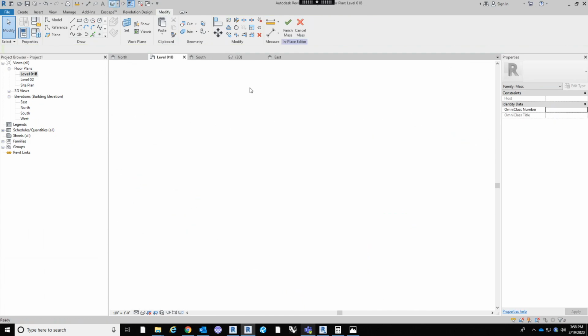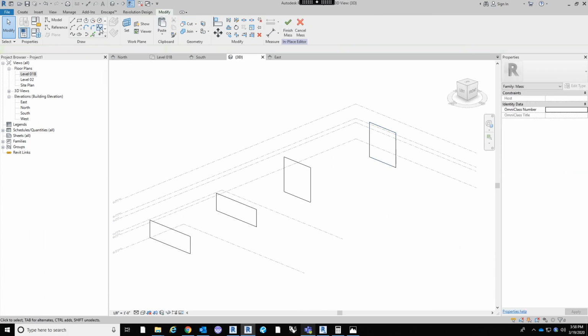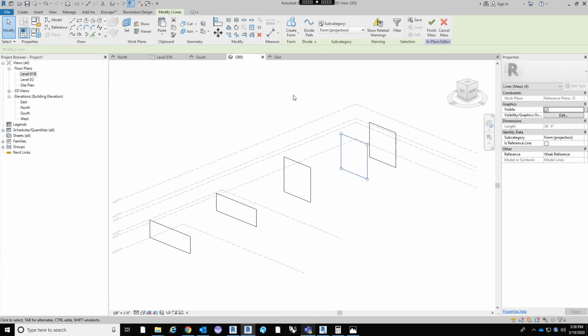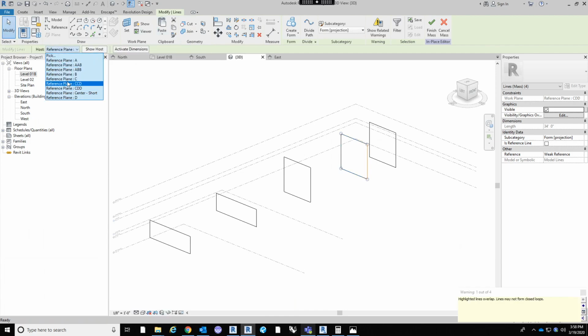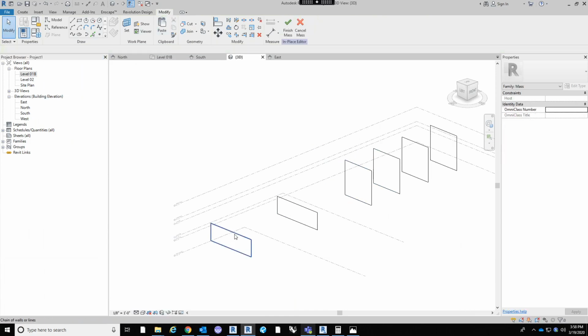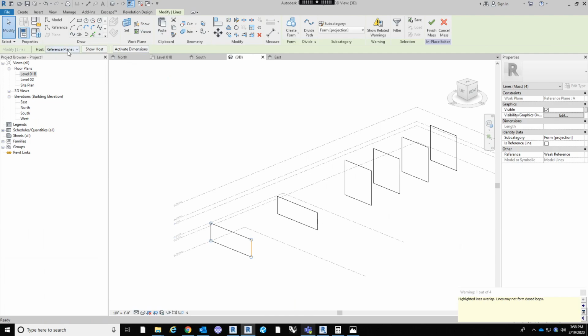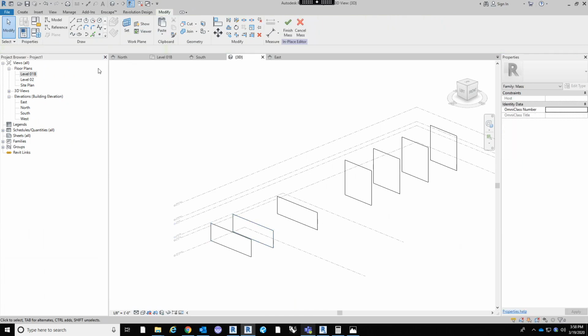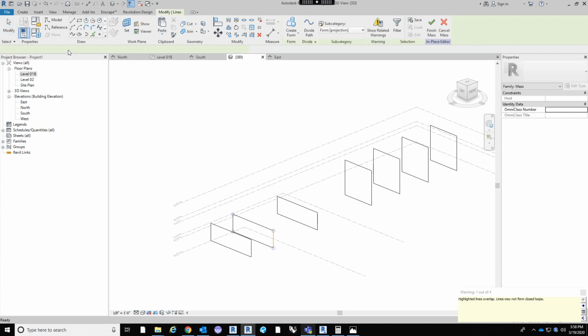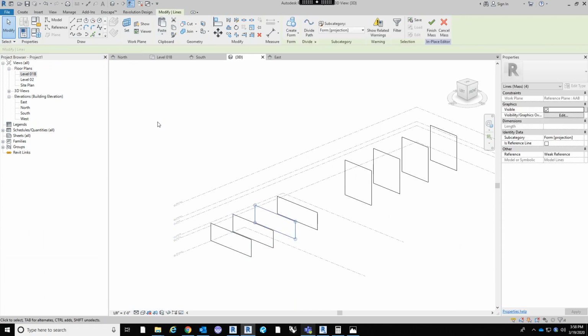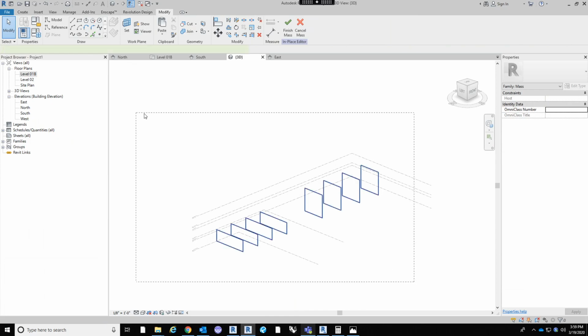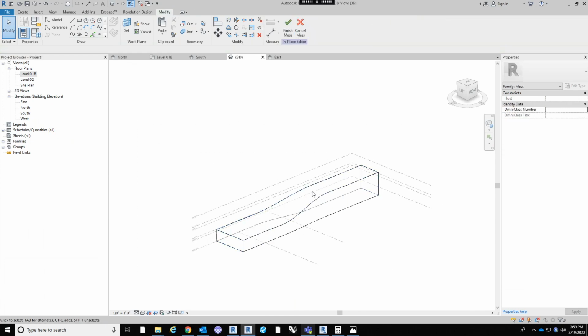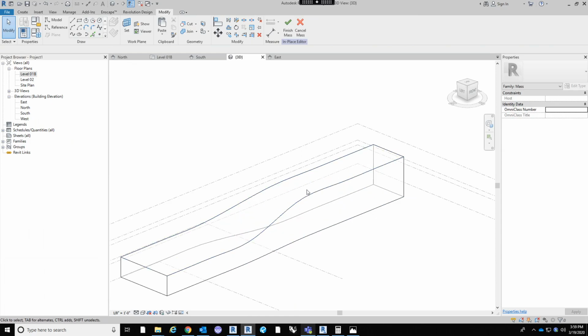Okay, so then go into our 3D view, copy, paste the same place, change the reference line to CDD, and then do the same thing, copy, paste the same place, CCD, then do the same thing with the shorter guy, copy, paste, same place, AAB, copy, paste same place, ABB. Alright, so then we can highlight all of these, hit create form,